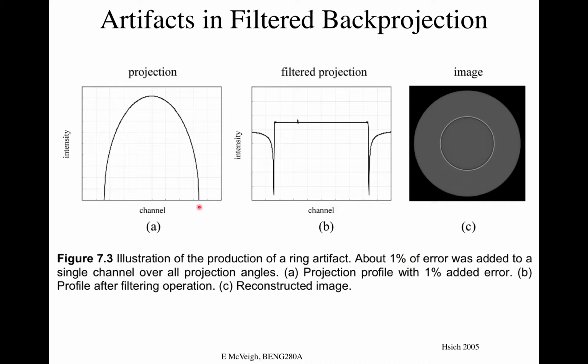So you can see why this whole set of detectors really has to be essentially calibrated every day. You go through and look at the gain on those detectors every day and before every scan if you can, and then you normalize your signal to the measurement of what the gain is on that detector at that time.